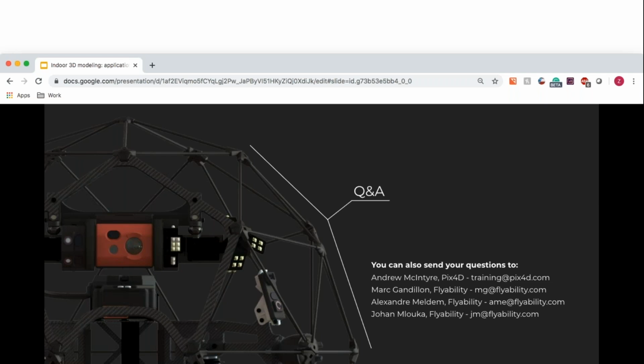Now, if everything has been tied together correctly, because that's what Pix4D Mapper is trying to do when it's processing your photos, then we expect, under normal circumstances, that the accuracy of any measurement within the reconstruction will be within 1 to 3 times the average ground sampling distance of the images. That assumes that the information you're using to scale and orient your reconstruction is as accurate, if not more accurate, than the ground sampling distance of your photos. But that's typically the rule that we apply when trying to estimate the accuracy of the project.